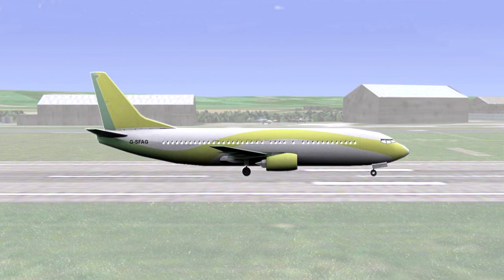In order to better understand landing performance, we need to analyse the forces acting upon the aeroplane, and how these forces might be modified throughout the landing. The first of the forces that we will consider is weight. As you have learnt already, weight acts vertically downwards towards the centre of the Earth from the centre of gravity. During flight, weight is mainly balanced by lift. However, once the aeroplane is on the ground, weight is balanced by the reaction of the ground acting up through the wheels on the undercarriage. The weight of the aeroplane on landing will be less than at takeoff due to the fact that fuel has been consumed. There is, however, a maximum structural landing mass which must not be exceeded.